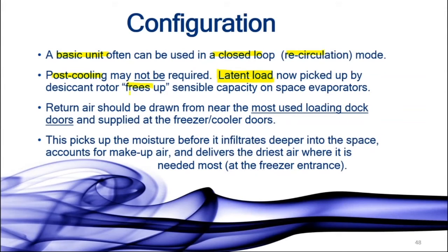And in doing so, it is going to free up, if you will, the sensible capacity to take on any heat that this desiccant dehumidifier may be providing to the space. So normally there is no post-cooling required. Now, if this is new construction and you want to eliminate the extra equipment of having evaporators in the loading dock, then yes, we would use post-cooling.